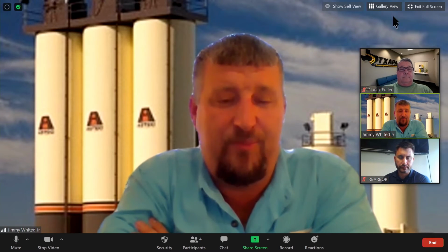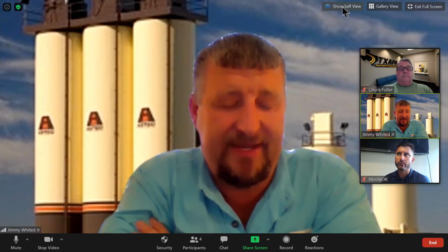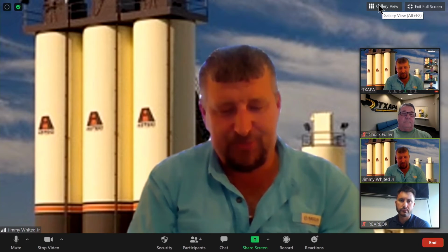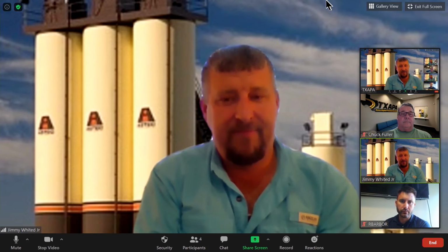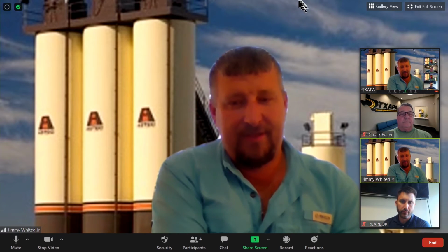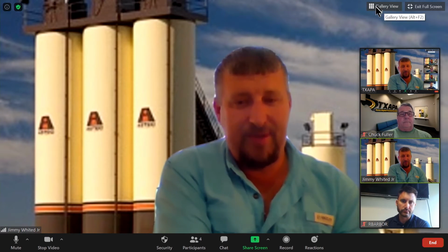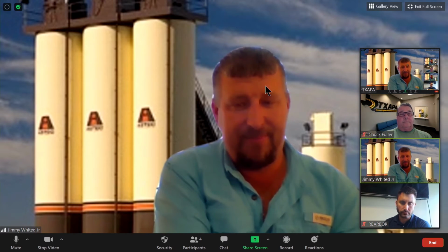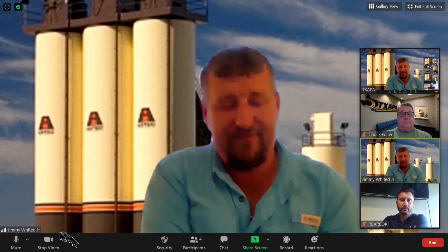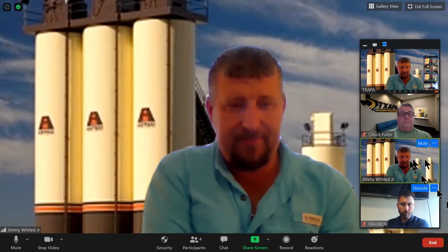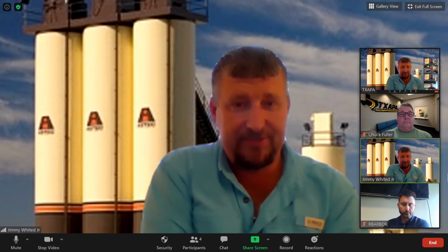This is where running stockpile gradations weekly, tracking all that, and watching what's coming in matters. Don't just put that mix right up underneath the top end. Push it down further, push it away from that 37. If we're talking about type C, 37 is max, so get down to that 31, 32. That way, if you're at 32 and you hit a fine pocket, it's only going to jump up to 34, 35. If it's jumping up to 34, 35 on the coarse side through a Superpave press, you'll still be within that plus or minus 1%. You won't be within that plus or minus 0.3%, but you're not going to be a remove and replace.